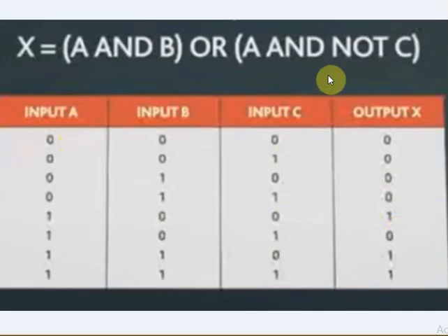Right, earlier I told you that you can put the group here, another column here, and compare this and write. In that case, where the ones are coming, you just put ones, and for the others you need not compare, we put all 0. Now in this case I haven't put any extra columns. I have written all the combinations for A, B and C, right? Then I am directly writing the output.